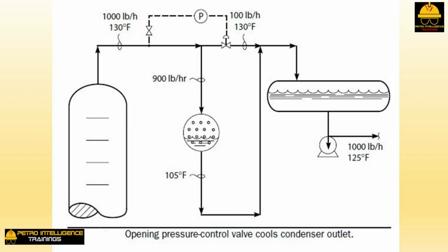As the hot vapor bypass valve opens, the condensate level in the shell side of the condenser increases to produce cooler, subcooled liquid. This reduces the surface area of the condenser exposed to the saturated vapor. To condense this vapor with a smaller heat transfer area, the pressure of condensation must increase. This, in turn, raises the tower pressure. This, then, is how opening the hot vapor bypass pressure control valve increases the tower pressure.